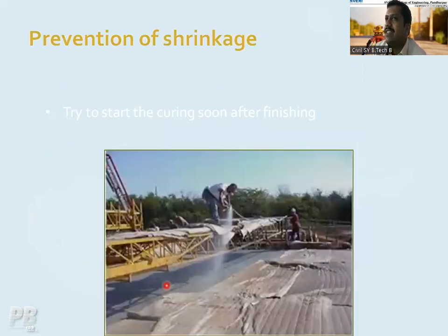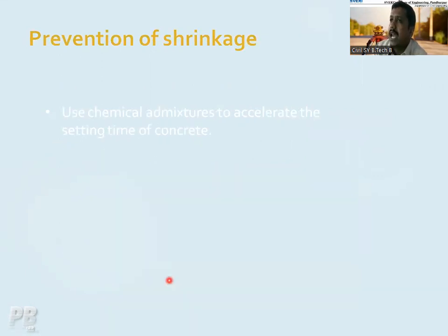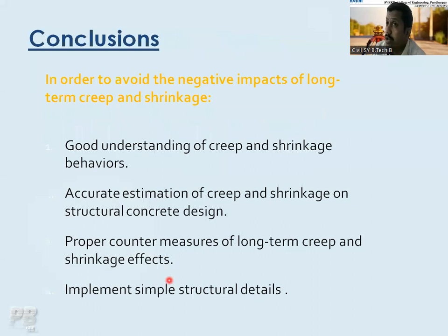Then the next technique: try to start the curing soon after finishing. Immediately after finishing, you must start the curing of the concrete. Use chemical admixtures to accelerate the setting time of your concrete.